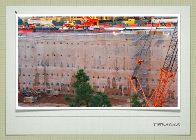So the tiebacks are pretty much permanent? Tiebacks are definitely permanent. For the cross-lot bracing and the rakers, you take those out later on. So what happens is when you dig a hole for this excavation, you're anticipating building some kind of a foundation in the hole. That's the idea. So if you're using cross-lot bracing or the rakers, that bracing is temporary until you build whatever foundation walls you have. And then once you've built your foundation walls, they're going to retain the earth and support your building. In something like this, because the slurry wall is its own structural piece, you can build your building on top of it. This is the foundation wall. Therefore, these tiebacks become permanent. You're never going to take them down because that's what holds your building up in the first place.